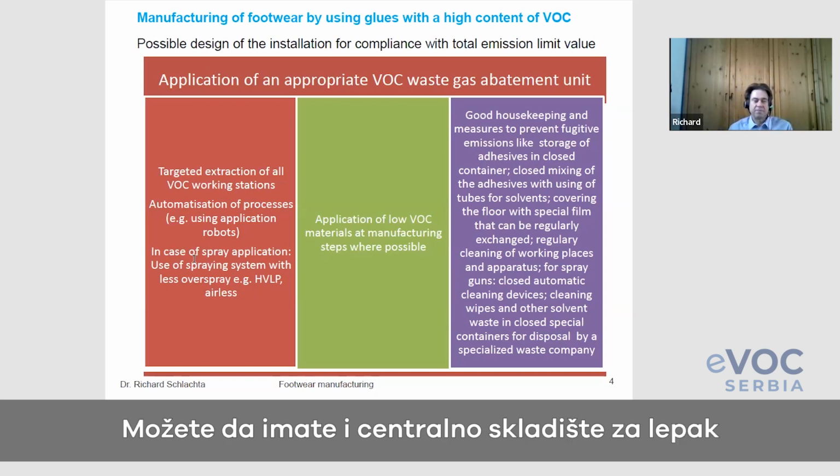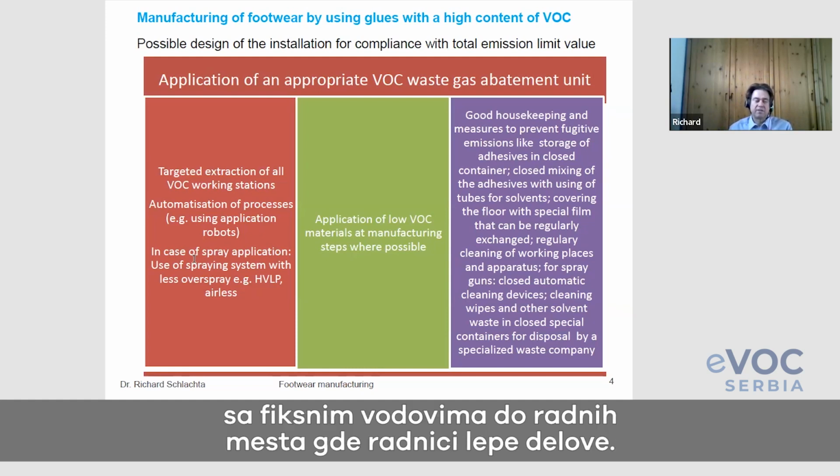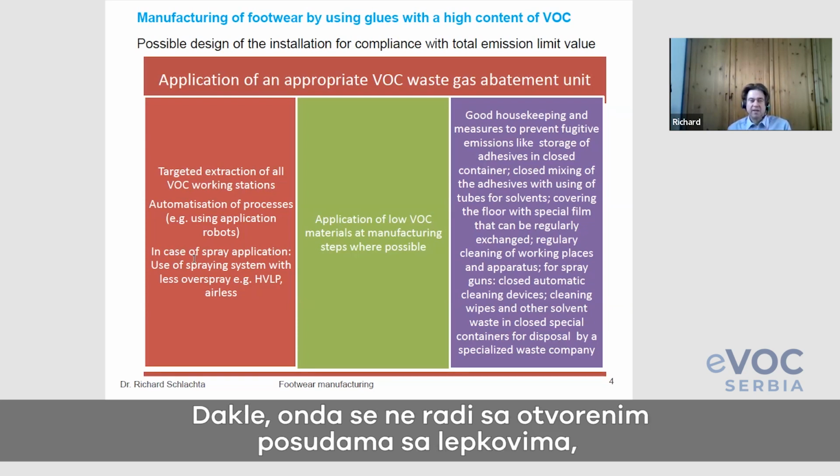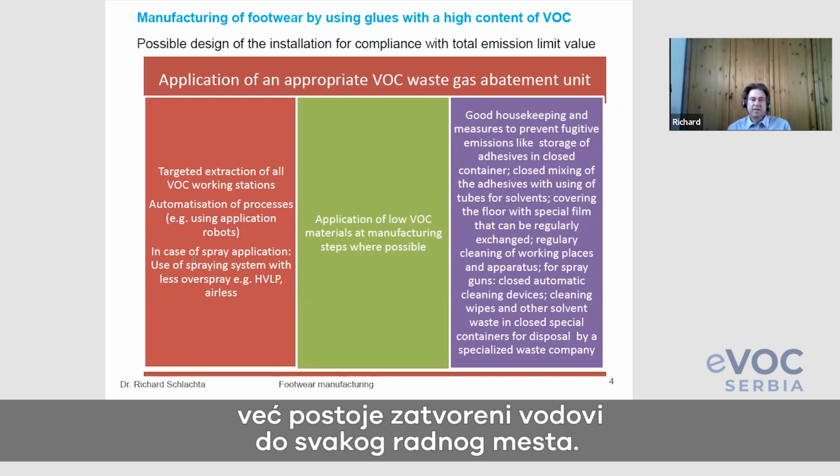Or you can work in a different way. You can have a central adhesive storage, with a container of the adhesives, and from there fixed lines to the different working stations where the workers are gluing the parts together. So it is not that the VOC containers are open-handled.